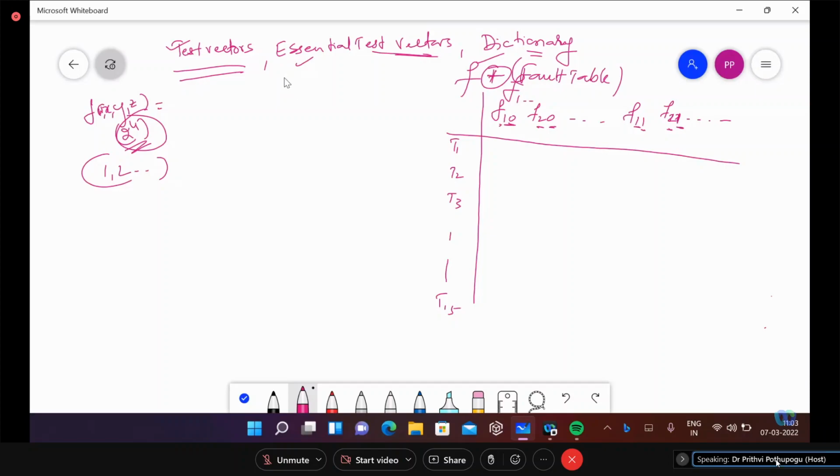So for that, I think we had the adaptive tree as well as the preset experiments, preset test. Okay, this is the branching aspect of pass and fail. And this is product faults analysis, wherein something like what we have seen is two faulty lines can nullify a fault. One faulty line with a fault-free line can generate a new fault. That sort of analysis we have seen. Okay, so this is based on the product faults.